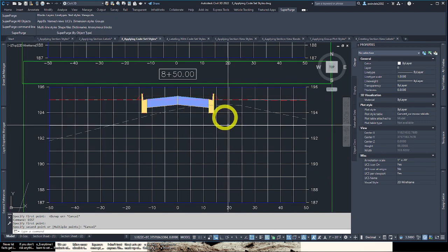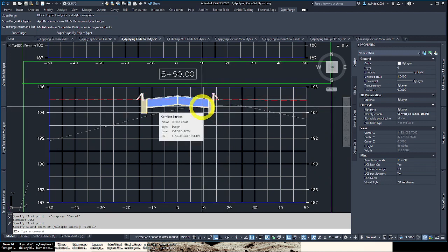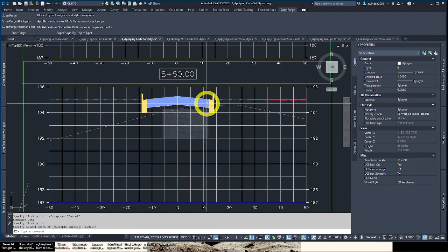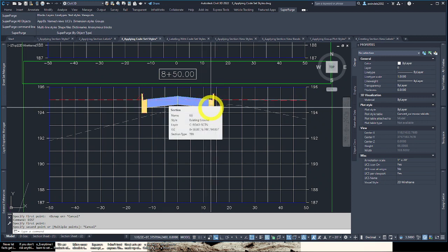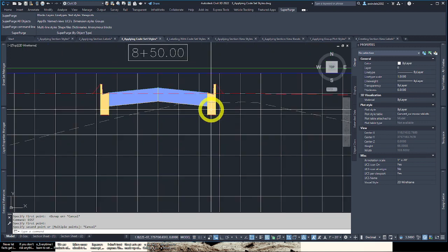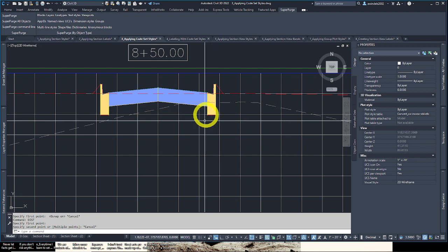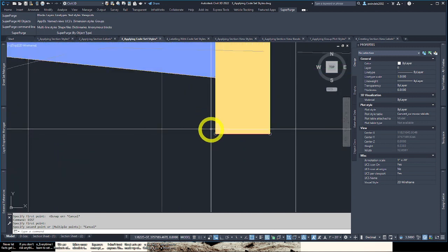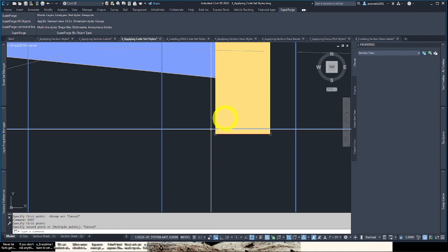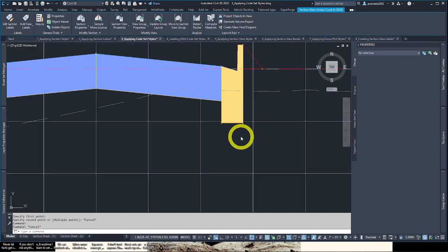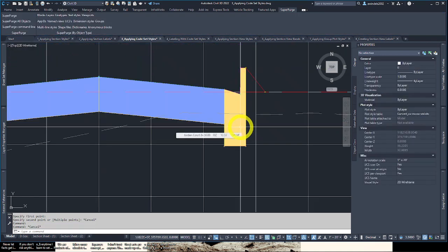A little review there. But these CodeSet styles, think of these as assemblies. They have smaller parts inside of them called subassemblies. So in subassemblies, even within them, it's like breaking the atom a little bit, right? They have within them points, links, and shapes. So basically the points, each one of these, the links, which link point to point, that in the end form a polygon, or as Civil 3D calls it, a shape. So they work together hand in hand, and they have at least one code assigned to them. And this line string of text is the key to how a code set style works.